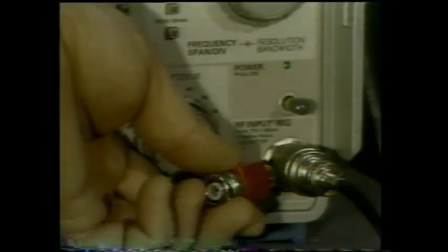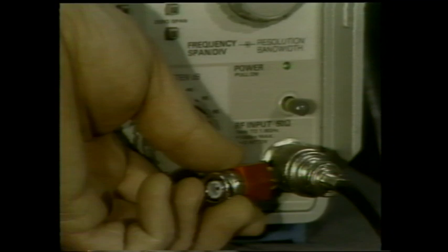Remember, the spectrum of most interference is made up of many different interfering pulses, so the display you get will not be as clean a spectral display as we got earlier. Another thing to remember is that the 496 is DC coupled, so don't apply DC to the instrument unless you use a DC block. It's possible that you might damage the mixer if you apply DC directly to the instrument.